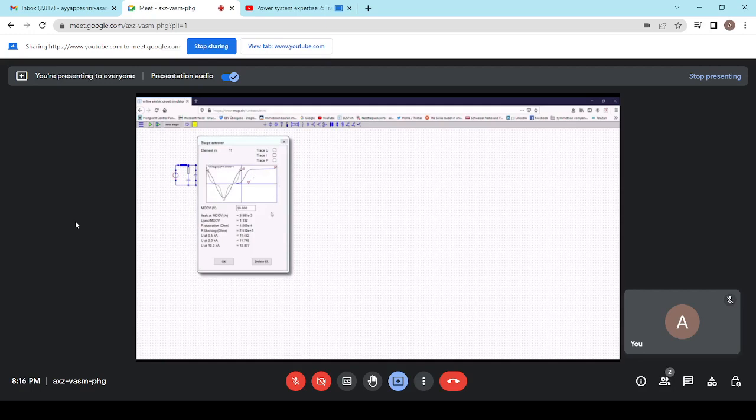At the surge arrester, I need to set the maximum continuous operating voltage. The nominal was 450, so for the maximum let's assume it is 500 kilovolts. Now I have 500 kilovolts, and I would like a protective level of, let's say, 1.5 per maximum continuous operating voltage. So I reduce this arrow here until I get about 1.5, and then the settings should be okay.